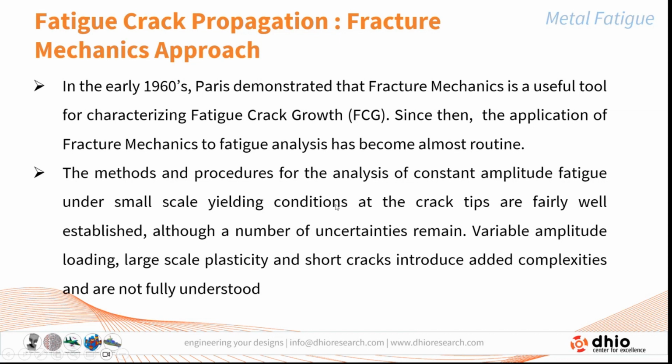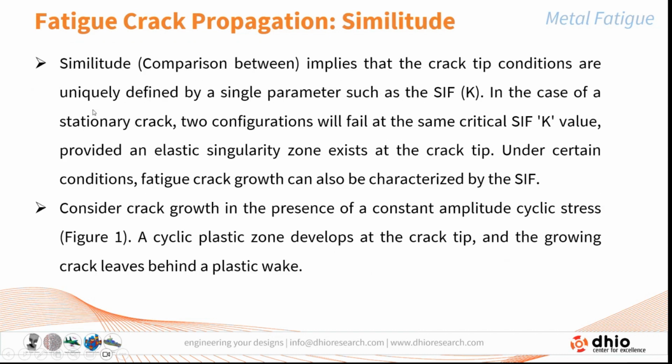The method and procedure for the analysis of constant amplitude fatigue under small scale yielding conditions at the crack tips are fairly well established. Although a number of uncertainties remain, such as variable amplitude loading, large scale plasticity and short cracks, which add complexity and are not fully understood even today.